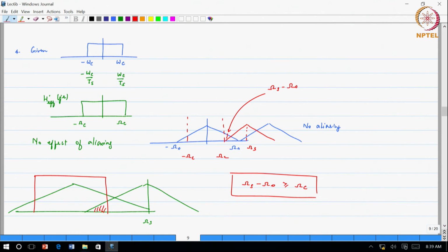So, in order for this particular example to work the way we have presented it, your input signal must be band limited to omega naught. So, the anti-aliasing filter has got a role to play there, but you have deliberately violated Nyquist because you know that you are interested only in a narrower portion, not the entire input spectrum. Right, that is a good question though. Yeah.